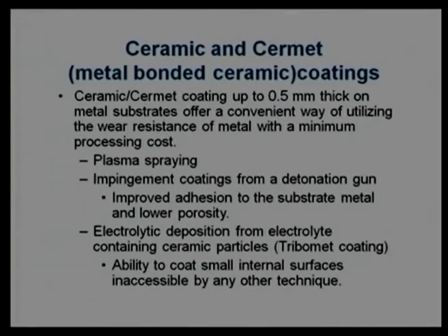The last solid lubricant we are discussing in the present lecture is based on ceramics. The good point of ceramic materials is that they have less chemical reactivity and high temperature stability. That is why this kind of lubricant can be utilized for high temperature applications, but they have a brittle structure. That is why we say that the coating thickness should not be more than 0.5 mm. More than this thickness, there will be fragmentation and fracture of that layer because of the brittle structure, and we should not use that.